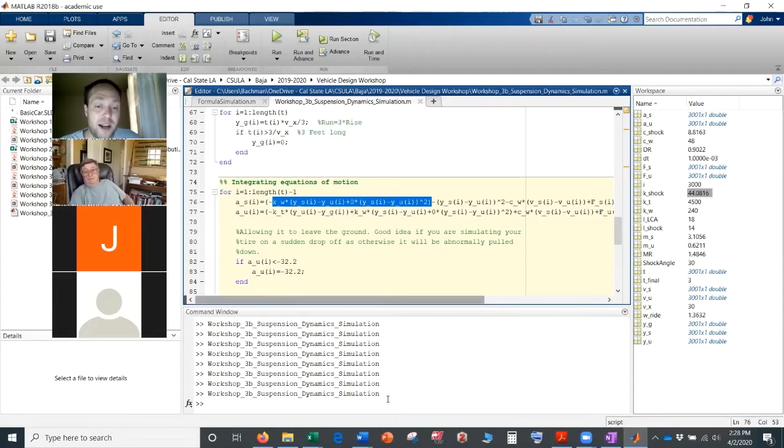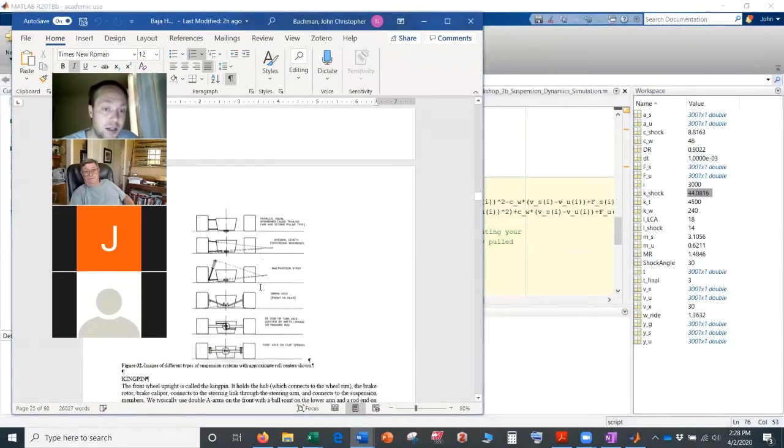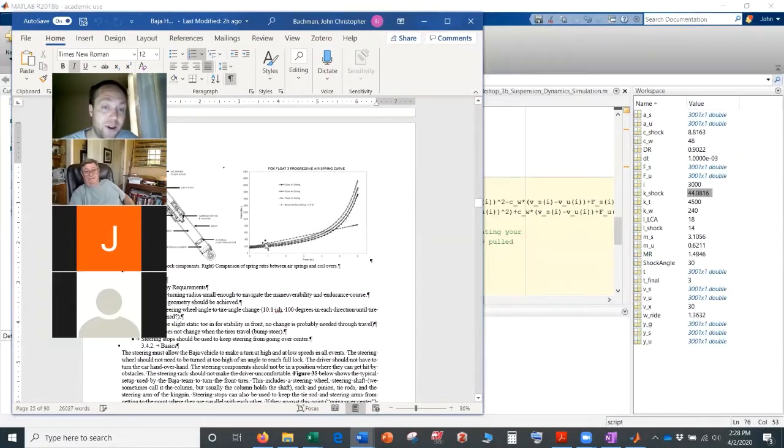So for example, our springs in our steering system, like Baja, right? The way our springs behave are these curves. They're not linear springs, right? So if you wanted to actually model a spring, they're nonlinear, which is good because you want a progressive spring so that you don't end up bottoming out, right? So progressive's good, and you either do this with two springs, air shocks, or your motion ratio can change. So we talked a little bit about that last time. But if you want to see more about how to get this progressively stiffer, because you want it soft down here, but when you get near the end of travel, you don't want to smash into it, right? So you'll have bump stops and you have progressive springs.